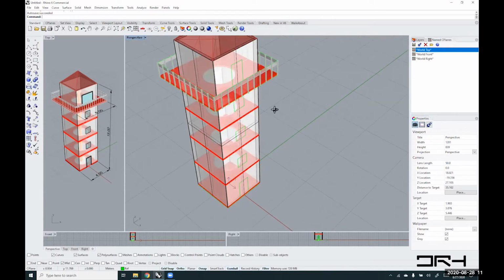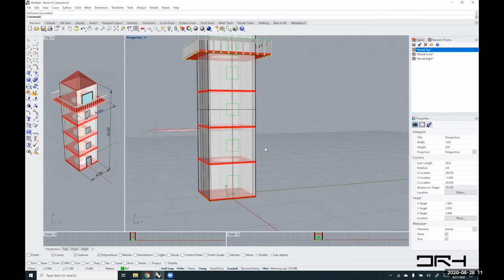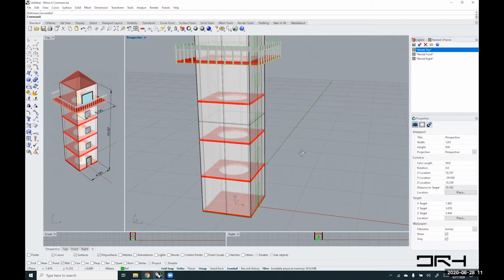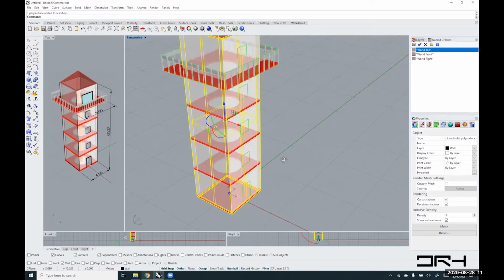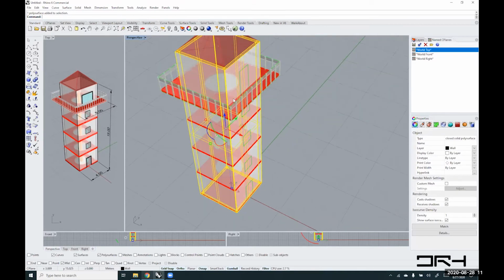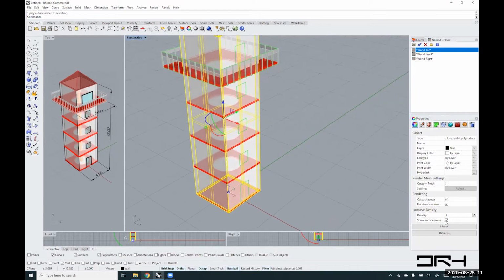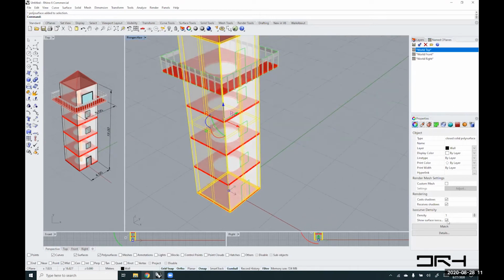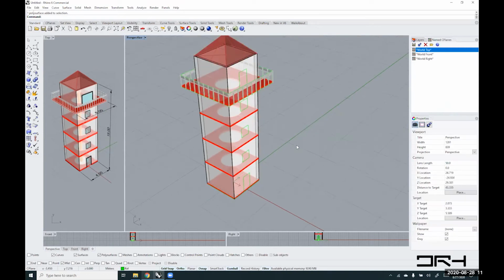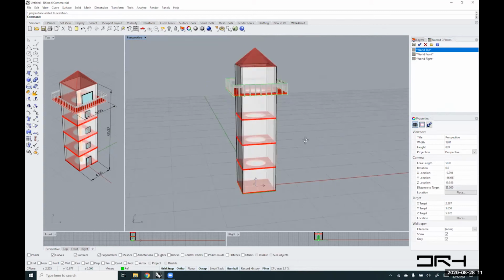And now I generated my wall with a thickness here, right? So that's a polysurface. If you don't want to see the ISO curves, you can select it and under the properties, you can untick the checkbox, show surface ISO curves. So it's actually going to read a lot cleaner this way.